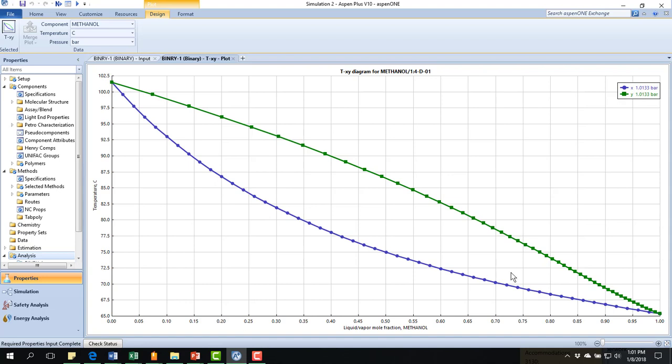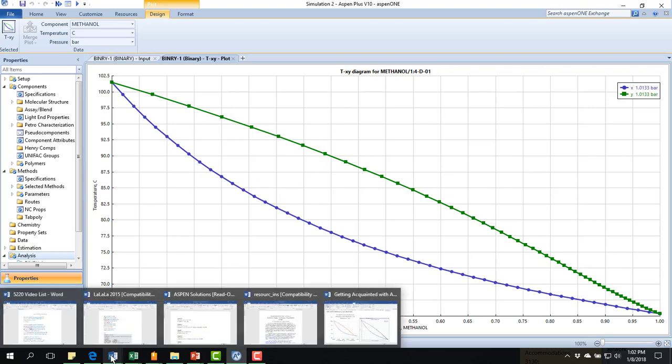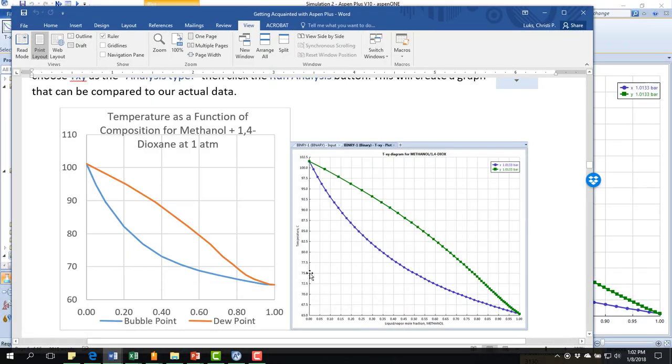And we have the picture here. And it does look more ideal at this end and a little pinchy at this end, not quite showing the azeotropic action that I saw in my other diagram. But my compositions are down in this range down here where it seems to be close to what I had. Now, I can do better, to be honest. Here we see them side by side, and I could do better, but this doesn't look like it's too bad as long as I stay safely down at this end.